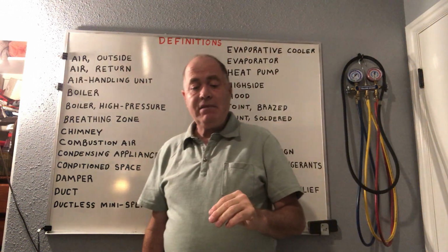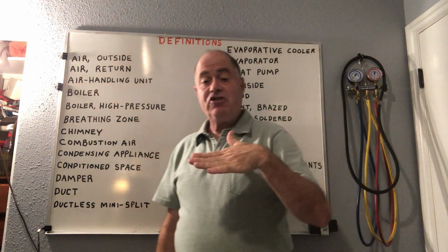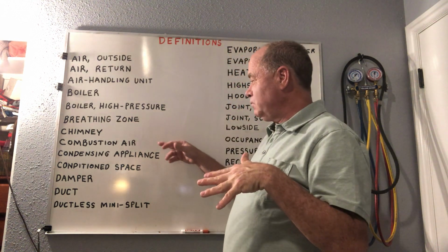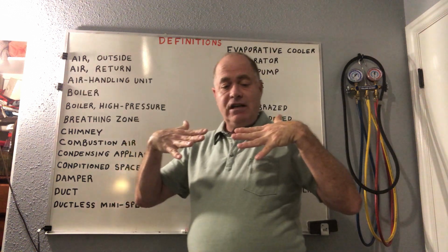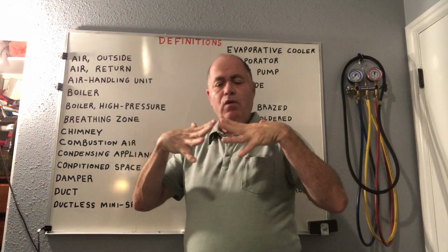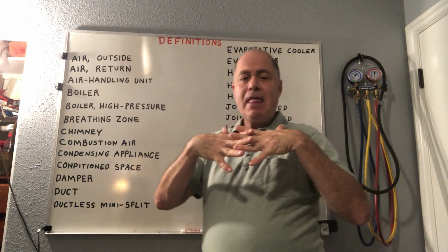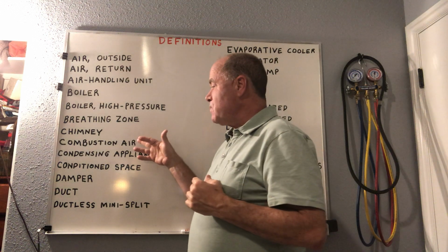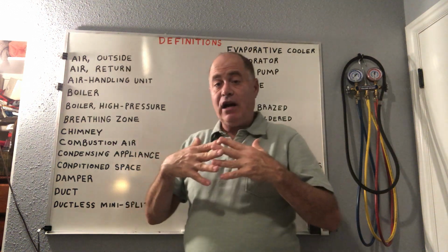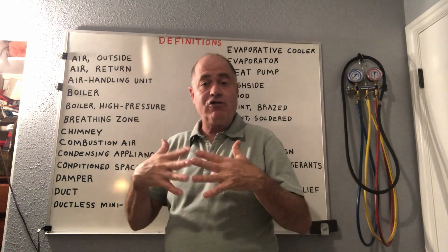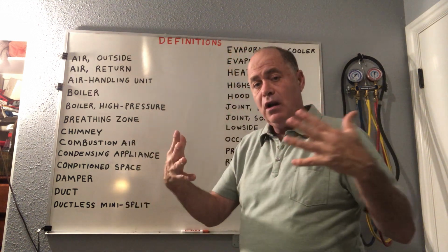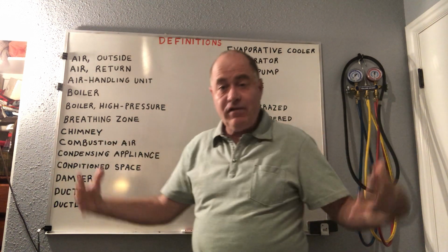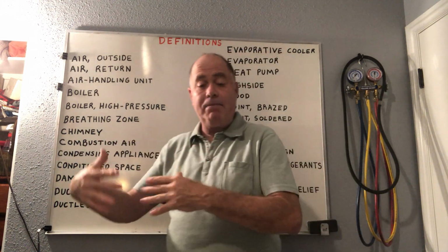So first you have combustion air, which is the air involved in mixing with the natural gas for combustion, right? Mostly it's air, 90% air or so, only about 10% natural gas, we'll say, for a hot water heater or a furnace. And when you mix those two together, you need to have a source of air continuously so that you can have proper combustion.